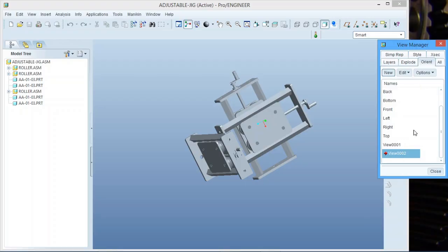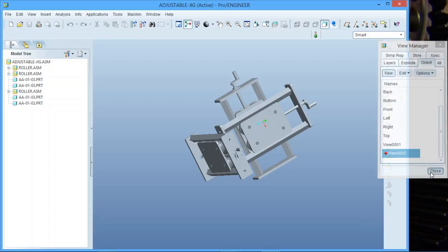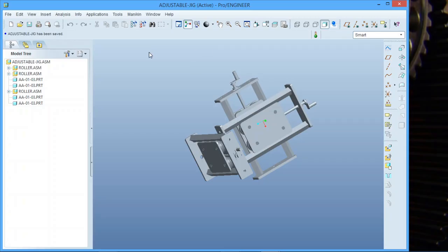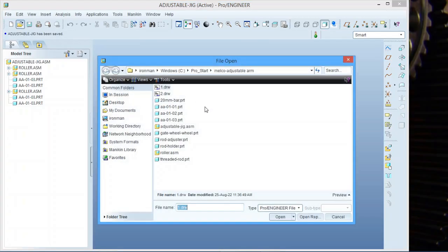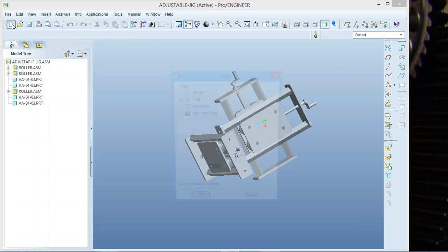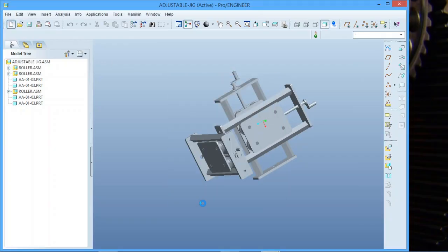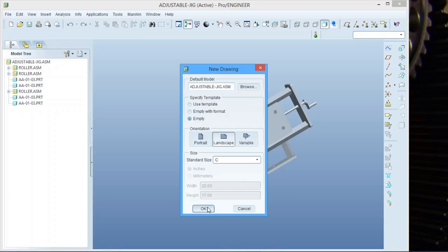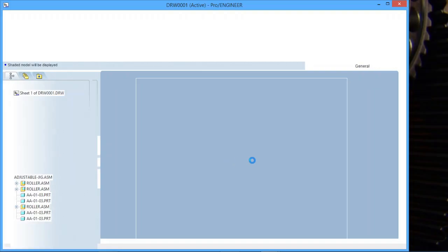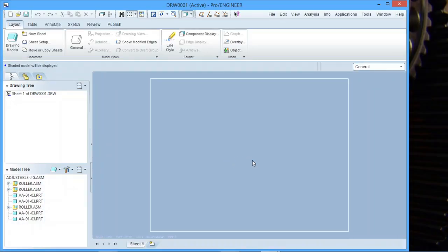And then all you're going to do, when you're done with this, is say close, say save, say okay, and when you open it now in your drawing version, so say I go to my drawing now. Oh, I don't have a drawing, sorry, we'll have to make one quickly. Let's go drawing. I'm just going to call it 1. This is just so I can show you guys what I was talking about with the menu. So now we are going to right click, insert general view, okay, paste.